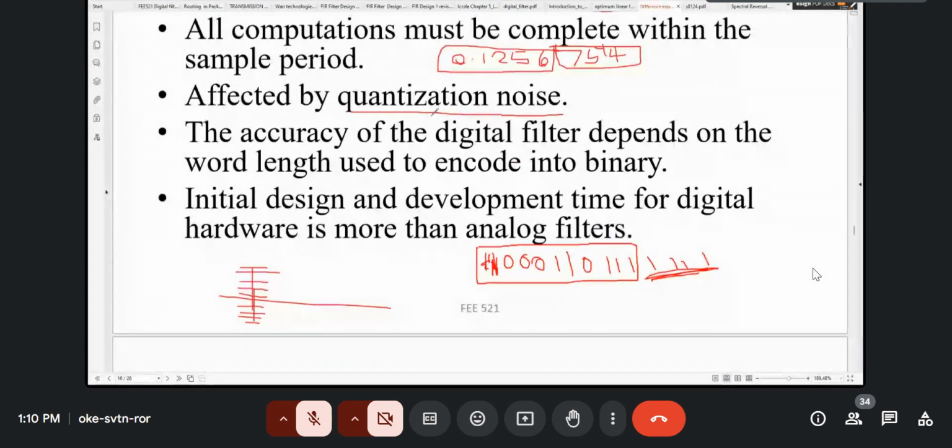Sometimes that is also referred to as quantization noise. The fact that you have cut off a part of the word of what you have stored in the computer. So this could be referring to both the quantization after sampling, or quantization of this cutting off of some of the numbers. I hope you have done computer storage, different types of computer storage, how you keep the floating point numbers and all that. I think from that you can see what I'm talking about.